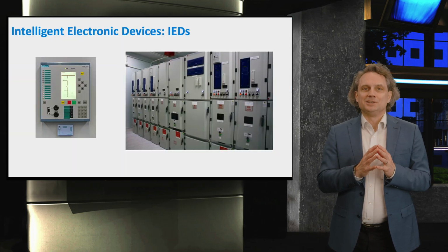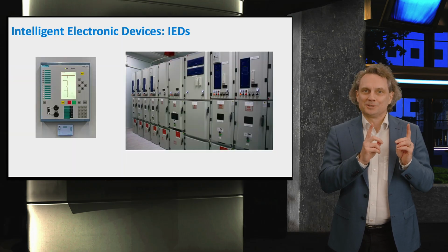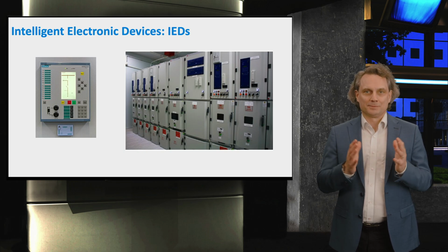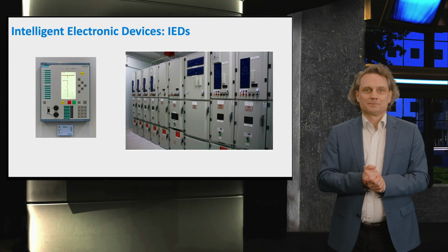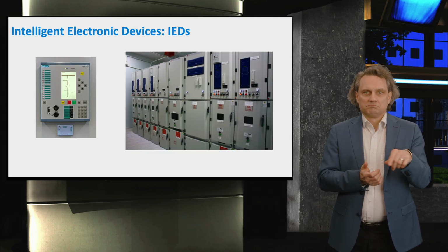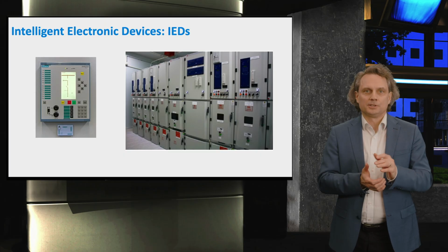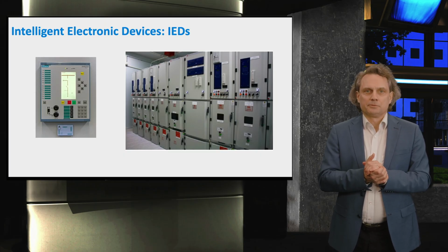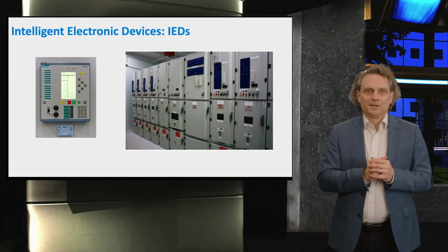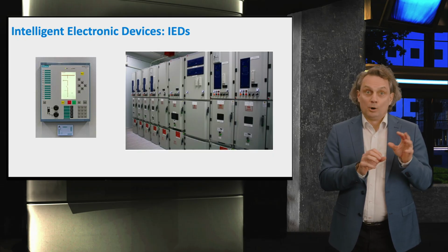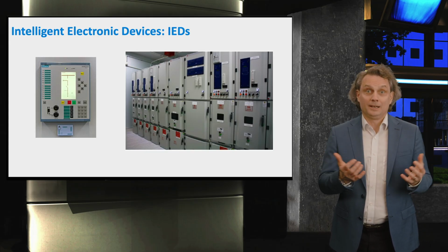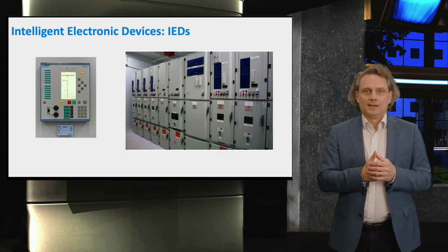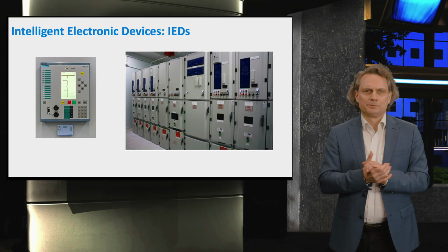The moment we use IEDs, intelligent electronic devices, we create a digital substation. All processes are based on digital controls and are easily configurable via networks. Some functions can even work locally without the control center in the loop. Local networks connect these IEDs that perform the respective function. All measurements are digitized and offered to the control network, and all primary elements, such as the switches and transformers, have a digital module that enables remote operation.